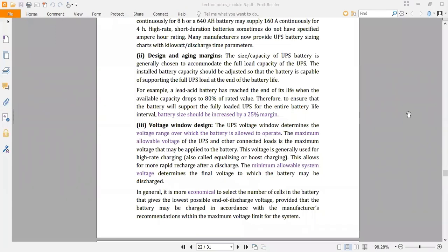अगर हमारा एक बैटरी है, उसका डेप्थ ऑफ डिस्चार्ज अगर 80% है सपोज, इट मीन्स व्हाट डज इट मीन? It means that if the battery is fully charged, and we connect that battery to a particular load, then it will discharge up to 80% of its full rated capacity.